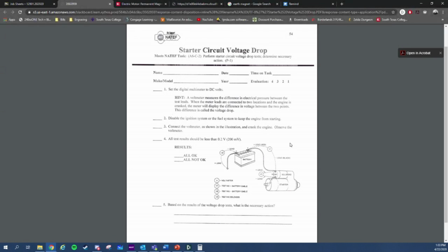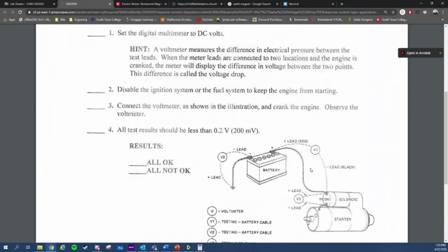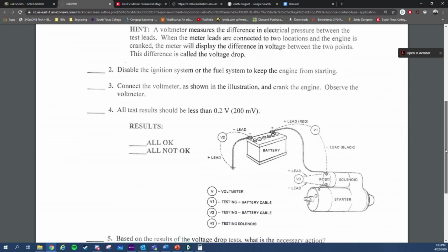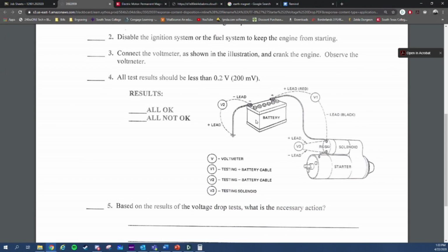So now if you look at this model, I want you to study this. Where are we checking this circuit from? Here to here. Where is that checking? From ground to the negative lead. Yeah. So your ground from your battery to your ground, either your chassis or your engine block, depending on where it's at, right? And we're gonna go over that right now.